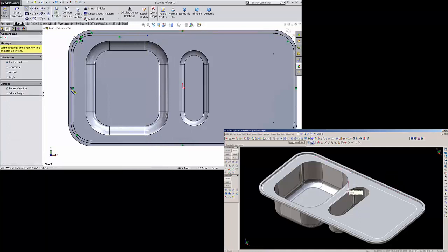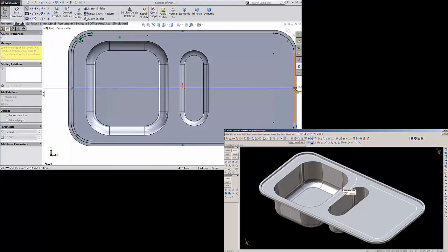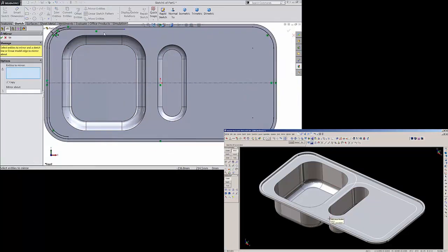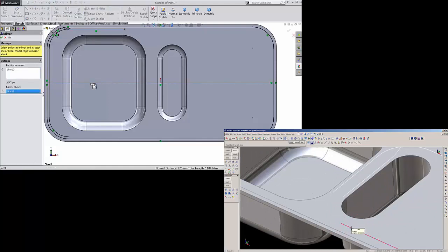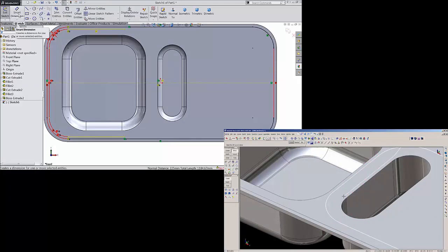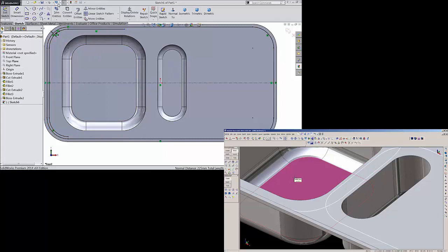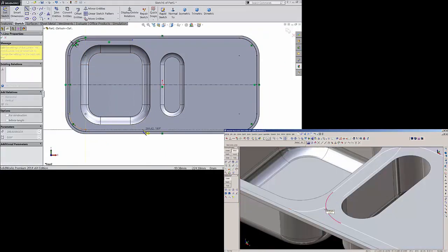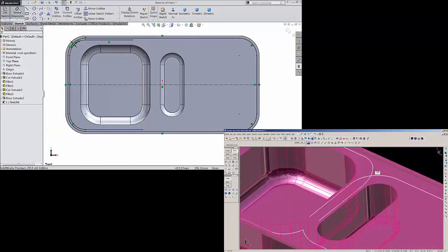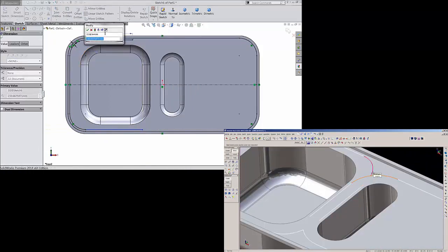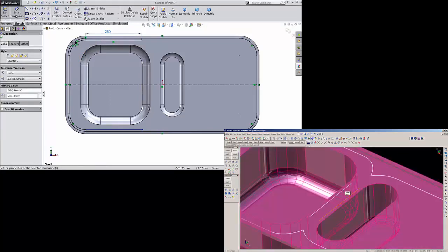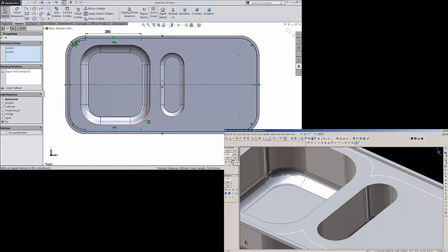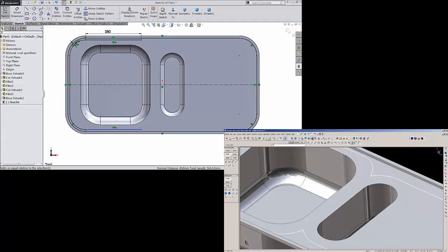Select a line, draw a horizontal line. Let's draw a construction line, vertical construction line. Just try to mirror this line against center line, okay. Reverse, better to draw it, and define this length 280 mm, okay. Now select this line and make relation equal, okay. Now choose spline.